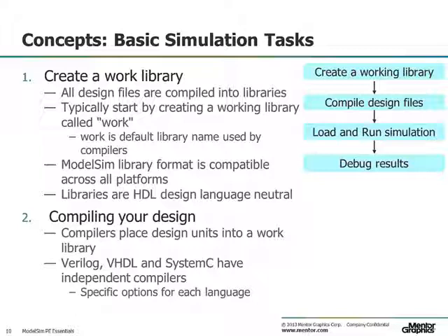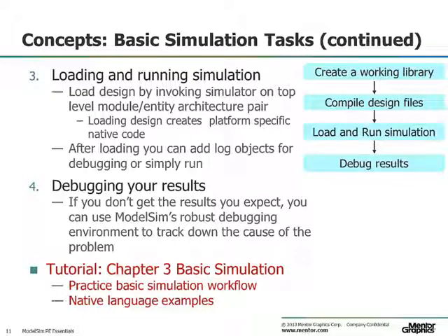The next phase is compiling your design. Our compilers have file-based syntax checks, and all direct their results to a work library by default named Work. Each compiler has specific options for the language, like what IEEE standard the compiler should check when parsing a design or test bench file. The next part of the flow is loading and running simulation. You invoke the simulator, vsim, with a top-level working Verilog module or VHDL entity. You can invoke with multiple tops if you architected your environment this way.